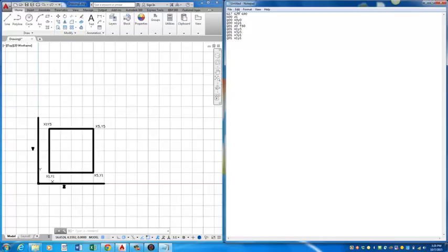Now we're not quite done yet though. We have to end our program in a safe condition as well. So I'm going to go with a G00, a rapid move, Z1. Lift the pen up. And if you want to, not everybody does this, but I do sometimes, I go with a G00, X0, Y0. Just puts my machine back to home when I'm done with it.